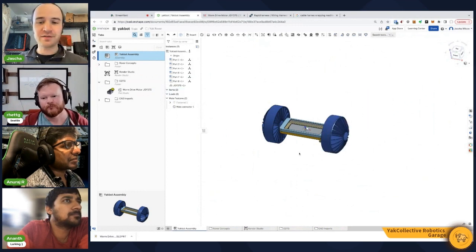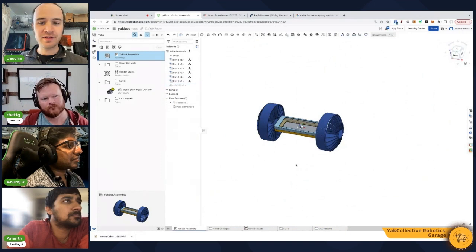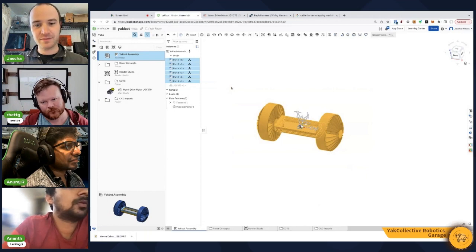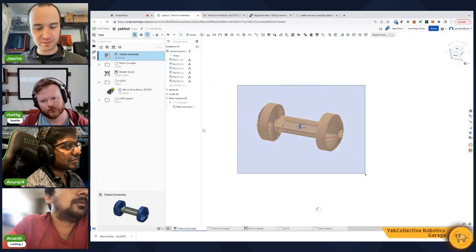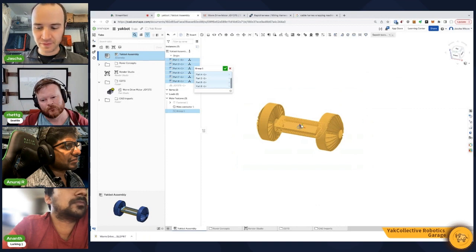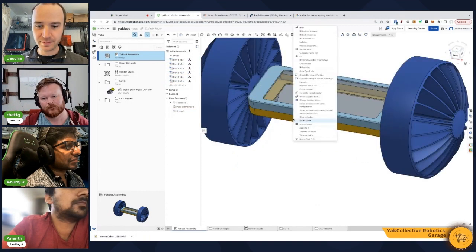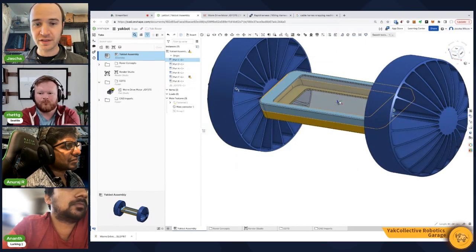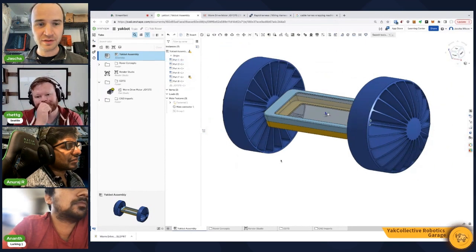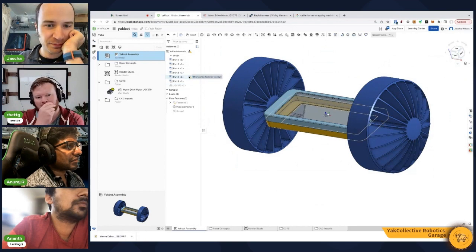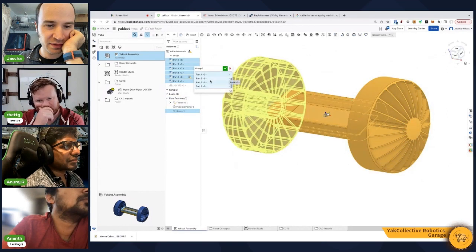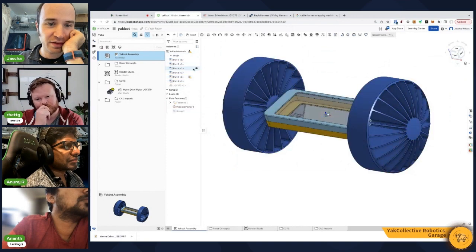If I did want to make sure I didn't accidentally drag anything, I'd select all of these and group them, and then we'd fix one of them. Now this is a group of things that are glued together as far as the MCAD tool is concerned. Oh, did I accidentally... Okay, I over-constrained something somewhere.